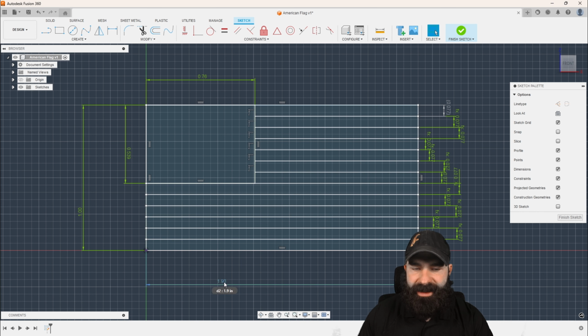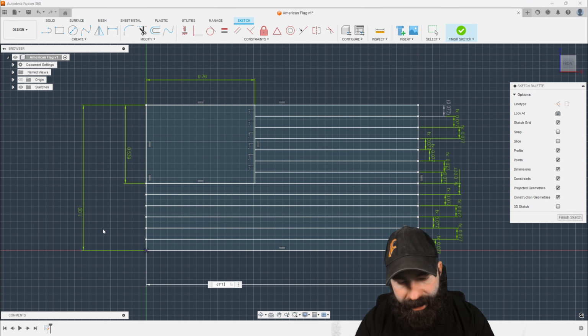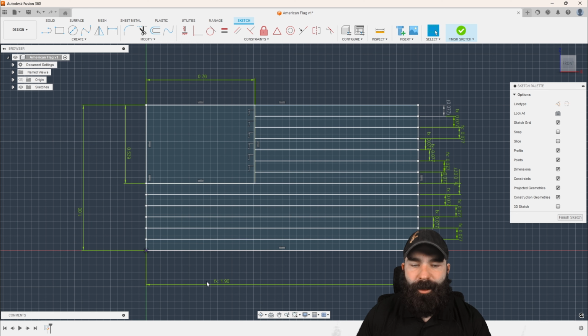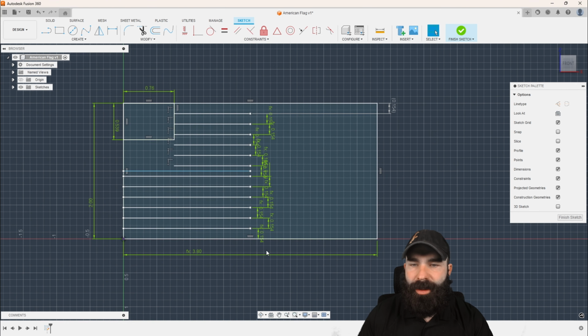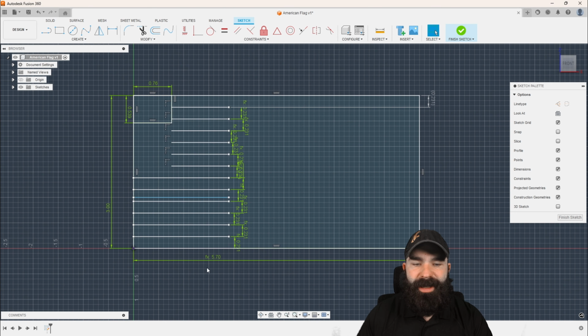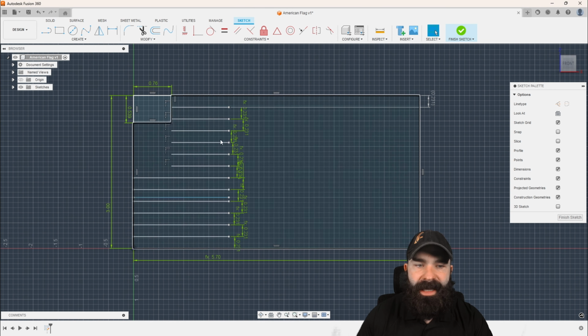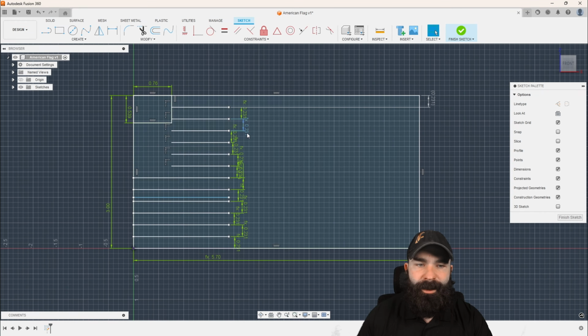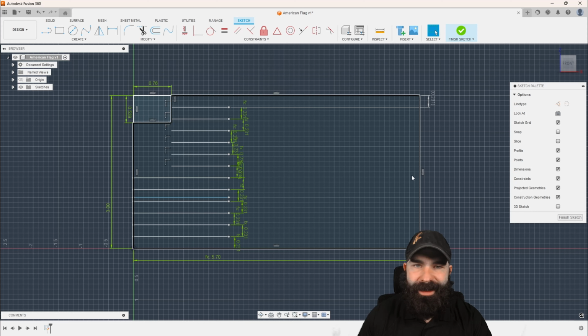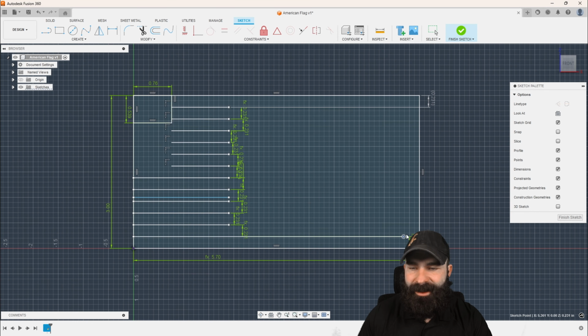What I'm going to adjust is this dimension right here, which is actually going to be dimension 1 times 1.9. The reason for that is if this dimension goes to 2 and I hit enter, notice how everything kind of blows up and expands, right? So we're now 2 by 3.8. If I go to 3, we're now 3 by 5.7 when it comes to that flag size. But as you're seeing, my lines are automatically spacing for me. Don't pay too much attention to the fact that they're not fully extended. We can fix that. That takes nothing more than a drag and a snap to a location. And now you can see that constraint comes in nice and easily.